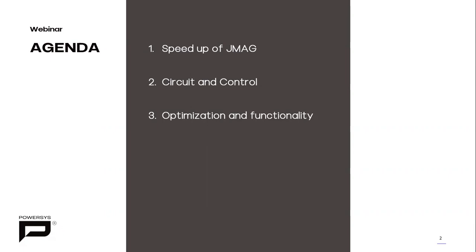And we can call our model here and go for different scenarios, like the thermal with water jacket and spray, the thermal with some other features, cogging torque analysis, and efficiency map analysis. Everything can be done in the quick express mode option as well as the designer mode option. That is the enhancement made for the speed up of JMAG.